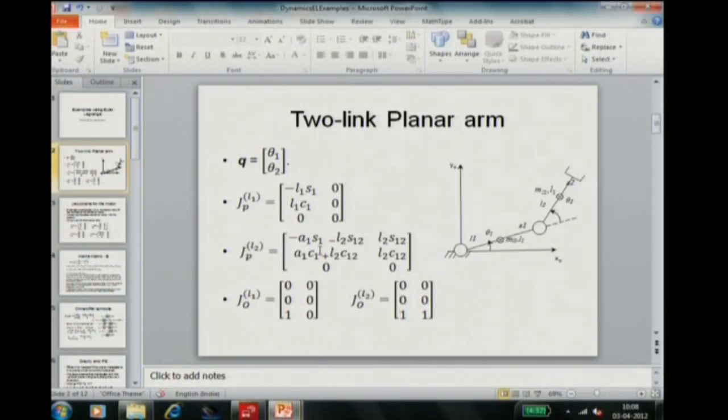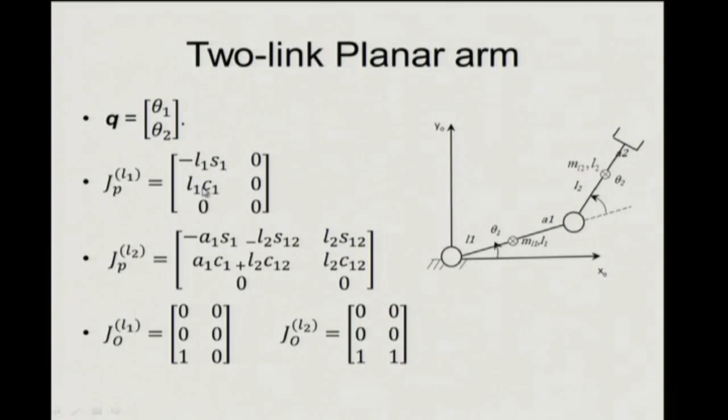So, now if you look at this term which is here, how will you get these terms? All the z vectors are along the z axis, so they are orthogonal to this plane which is here. So, when you take the product with respect to vectors which are going from here to here, what will you get? You will get two components, which are orthogonal to this line essentially. So, you will get a vector which is somewhere in this direction. It will have a x component and a y component, and you can check out that the x component is L1 S1 and the other component is L1 C1. So, these are the two components you land up with.